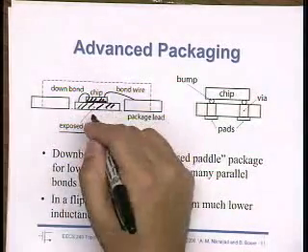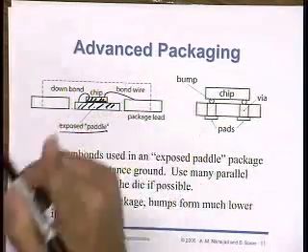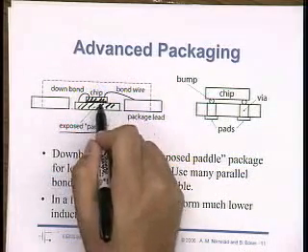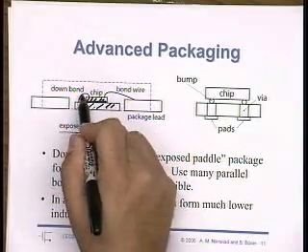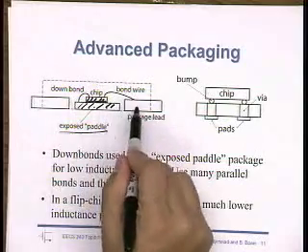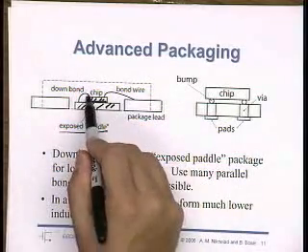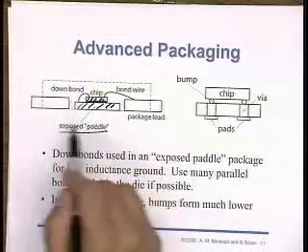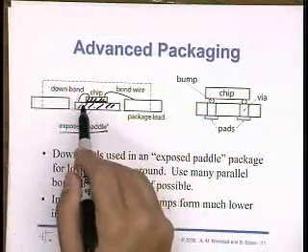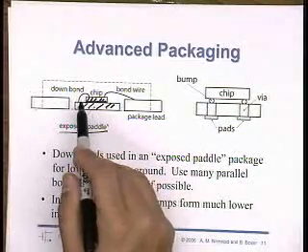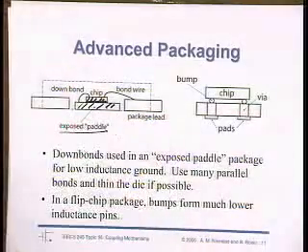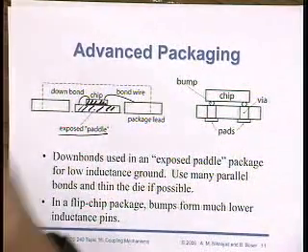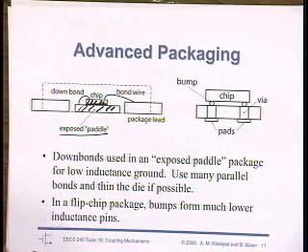And so now current can actually flow, so this grounds my entire substrate. It's something we'll talk about later when we talk about substrate coupling. But it also provides, even if I don't use a conductive glue, regardless of that, a very nice way to bring ground out from my chip. So instead of going through this long bond wire lead via, I go directly with a short bond wire, it's called a down bond, into this huge conductive plane, and then through a via to my ground plane. And I don't have to do this just once. I can do this several times, right? I can have, if I want, 10 or 20 ground connections, and each ground connection will reduce my ground inductance. Not quite linearly as you would hope, because they're mutually coupled, but considerably enough. Okay.